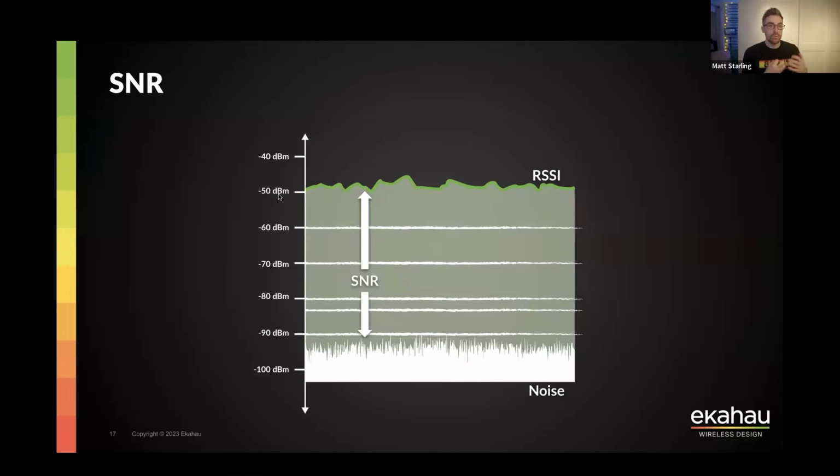And the higher the SNR value you have is a good thing, because the better signal quality that you have will typically mean that your device can do something that's called more complex modulation schemes, which effectively means that they can send their data transmitted over the air faster, because it's easier to decode those ones and zeros over the air. So that's what signal to noise ratio means. It can vary depending on how close you are to the access point, how much interference there is or noise in your environment will affect all of this, and naturally that will impact the speed and performance of your Wi-Fi.